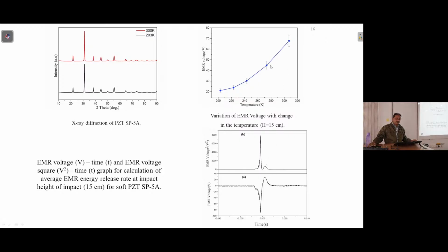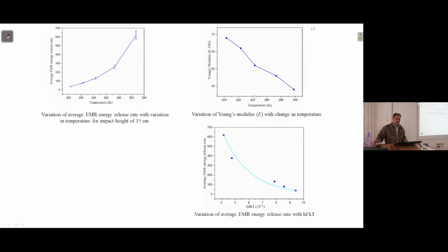And this decreasing pattern we had, a discussion about that we can have on the next slides. So in order to have a possible explanation, we had also conducted some mechanical tests. We tried to obtain the Young's modulus. For that we used strain gauges on the samples, and then we applied a static loading, and with the strain measurement and using the two values we finally got this Young's modulus.